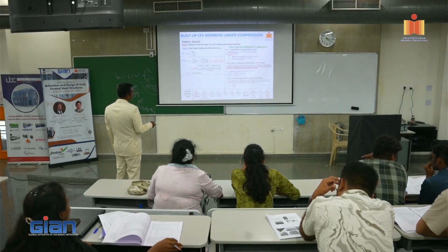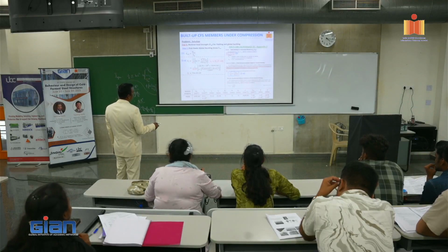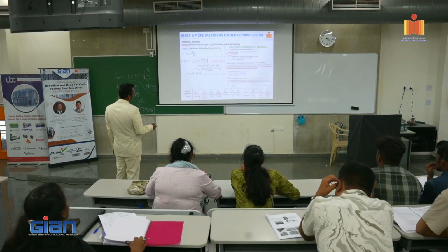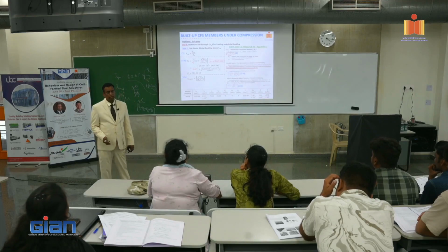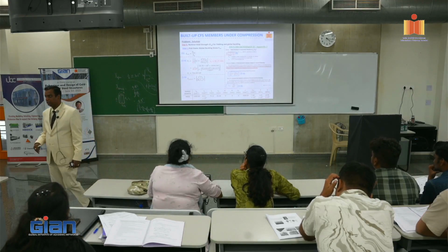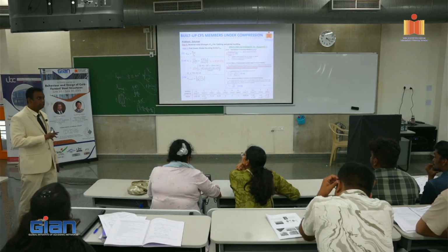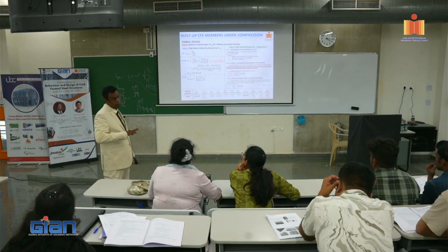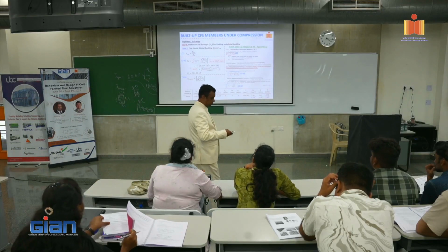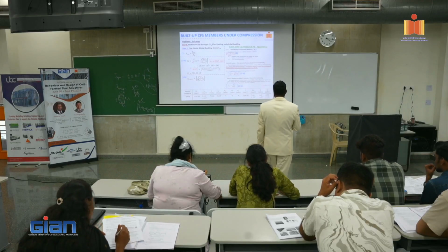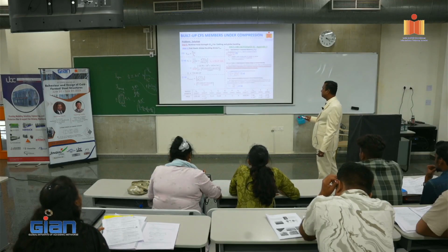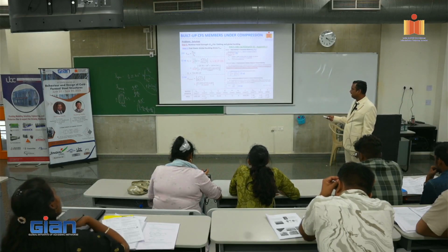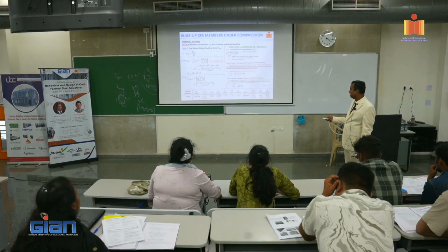Next one, we have to find out PCRE. It says pi square EI by KL the whole square. Now it can be KX LX the whole square or KY LY the whole square. We don't know which one it is. Flexural buckling can happen in the minor axis as well as the major axis. So let us find out both, right? Now we have PCRE equal to pi square EIX by KX LX the whole square. So what do we do here? Pi square into E, IX is 8.12, which we have already calculated, into KX. K is 1 into 3650.